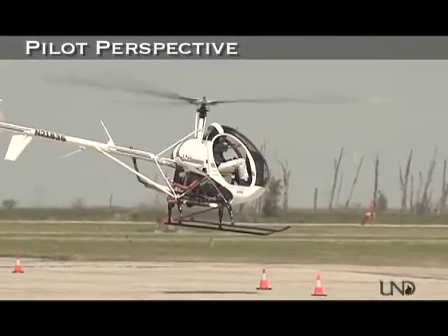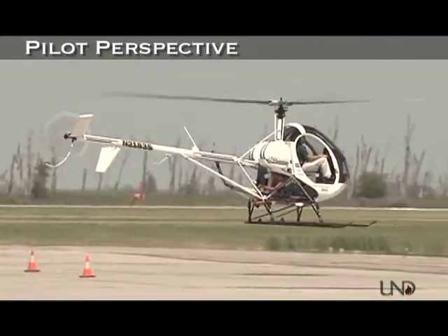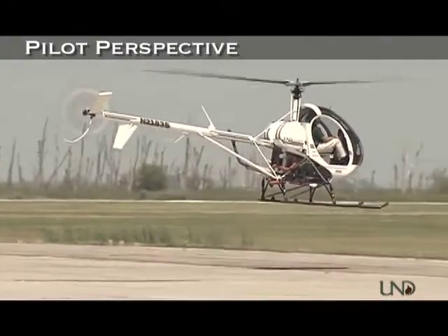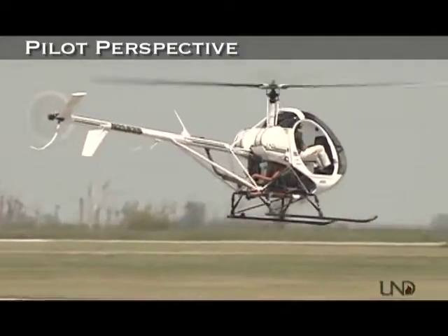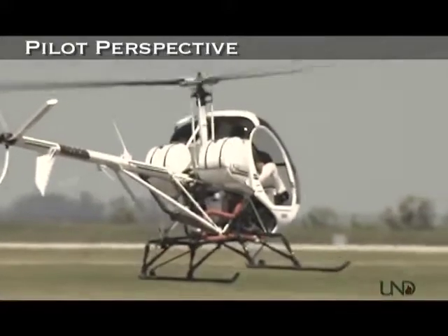Once the helicopter gets a clearance to hover taxi, we generally just point the direction that we want to travel and start a slow movement forward at a 3-foot hover in order to get to our area, somewhere between a slow jogging pace and a fast walking pace.